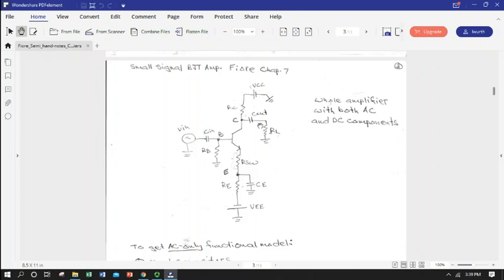We have our load resistor out here, and it's separated with a coupling capacitor because we don't want our DC to flow from this bias supply out over our load. We only want signal over our load. So we've got a coupling capacitor that basically says, nope, only AC can come out to the load. Because remember, DC will see a capacitor like an open.